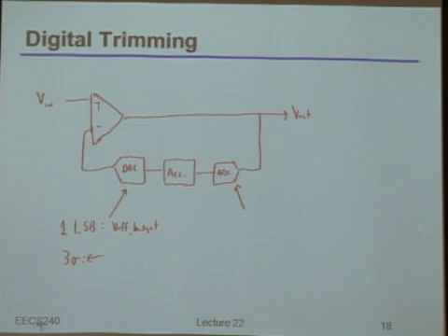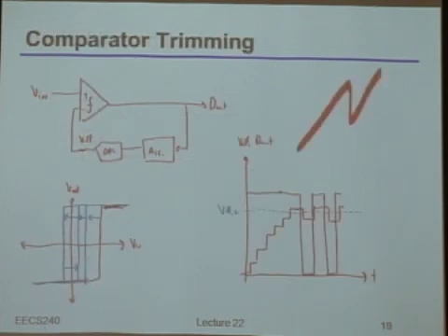All you really have to do, and let's be specific with the comparator as an example, is, of course, build the comparator itself, the DAC, meaning the thing that would actually physically affect your offsets, and any extra switches or anything you need to make the input actually go to 0 volts or to wherever your target offset actually is. Okay? So in other words, anything that might sit or interact with your high-speed signal path, that you actually do have to build. But anything that's digital control logic or some other thing that's off on the side somewhere that really doesn't matter, that you don't have to build. Is that clear?